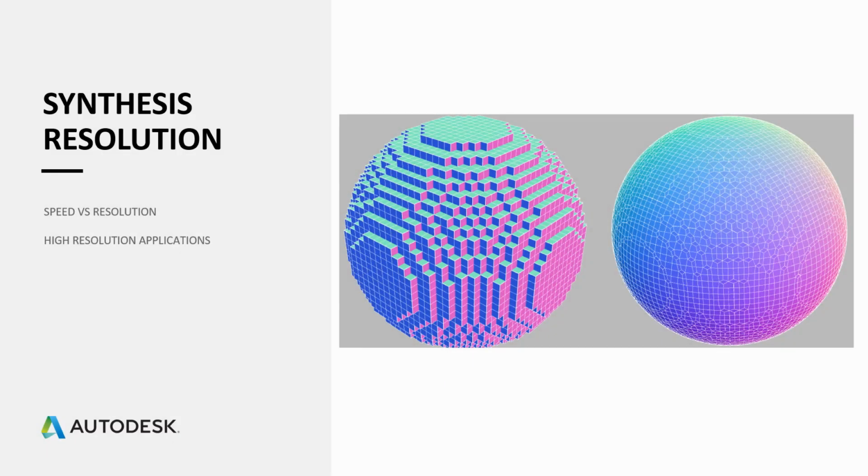All right, moving on to synthesis resolution. That's the resolution slider back at the setup phase, where you get to define essentially the resolution of the generative design study. There's 100 ticks on the resolution slider, and the default is 40. So you can see it's not a percentage or anything. It just goes from 0 up to 100, and the default is at 40.